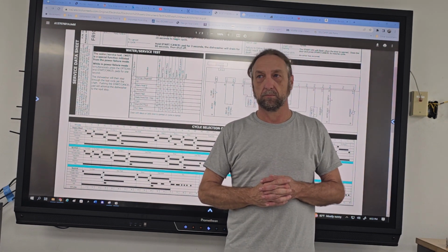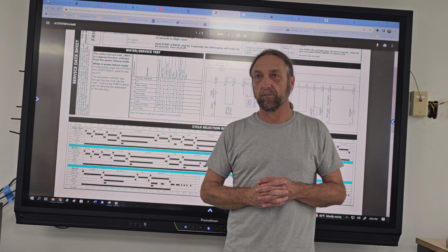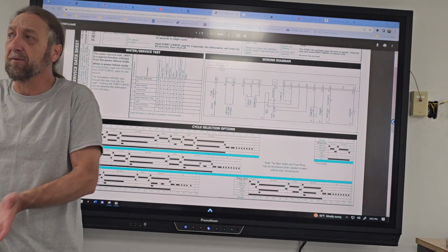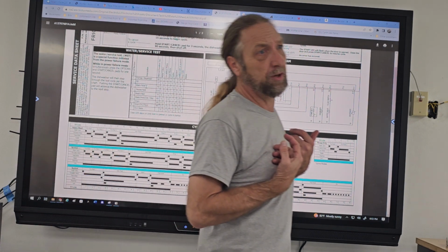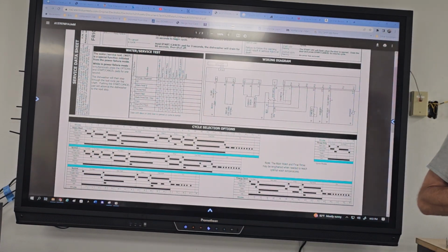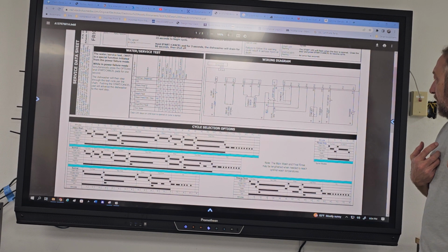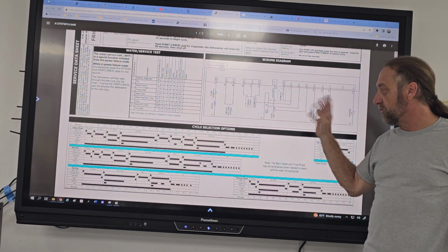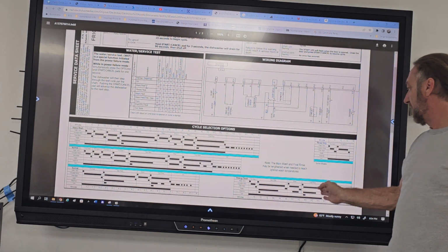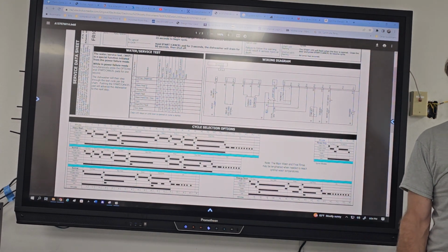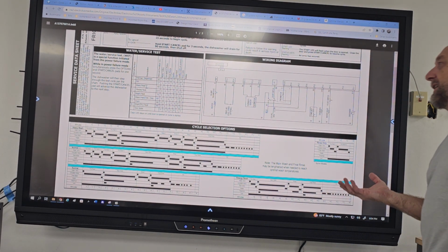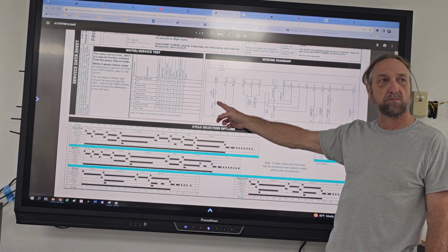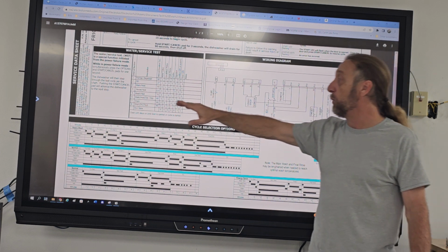Okay. Does that make sense? Yeah. So I don't have to wait 17 minutes, I only wait 1.5 minutes. That's reasonable. Right. I'm not gonna sit in the customer's house for 17 minutes. Now, another cycle is you could go into a cycle that's rinse and dry or drain cycle where it just runs the last half of the cycle. But if I didn't have voltage there at the heater, let's just say I waited 2 minutes.